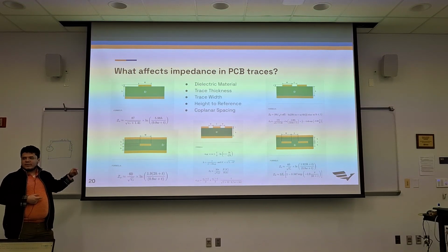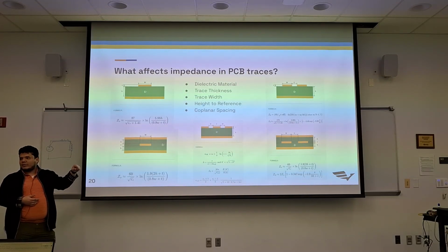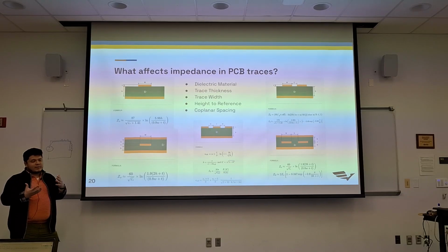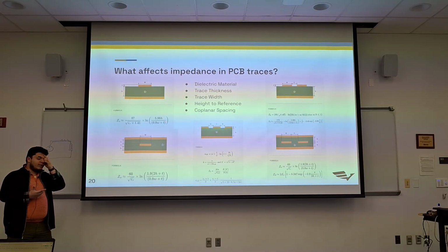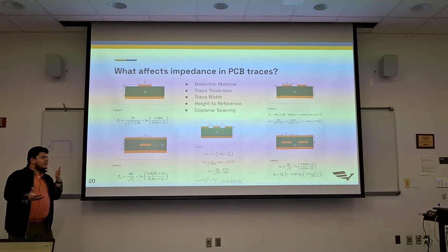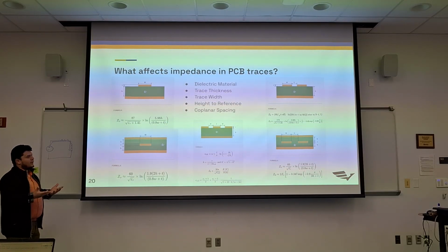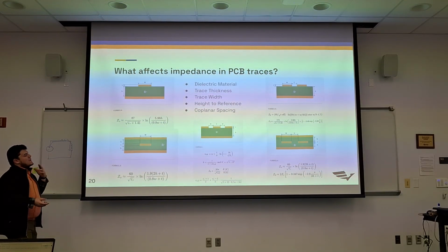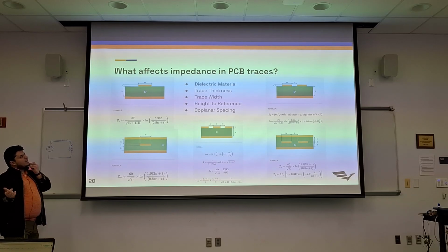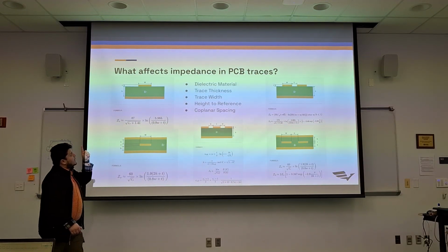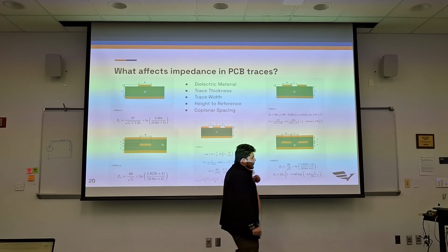Or maybe we can save ourselves a little bit, and with a 4-layer stack up, we only have 7 mils, right? So we can control that with the stack up, but work to see if that's something that you can afford. I don't think it's an issue, but sometimes time in manufacturing is going to be an issue. But the point here is, we can design for the track width.